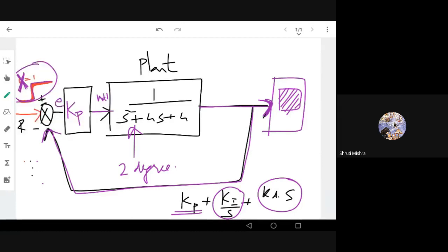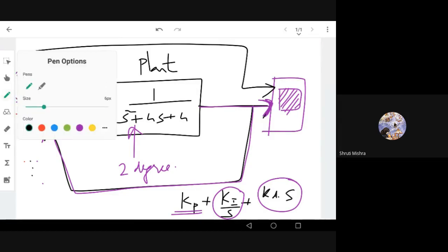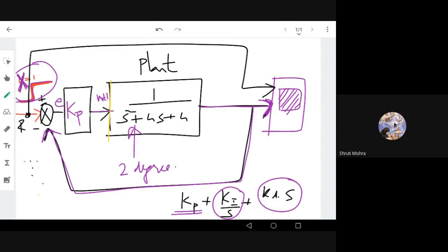So you also try to keep the reference signal in the scope. The two signals are given to the scope in MATLAB so that you can compare the change of output, etc. Right? So what we have done, we just made a transfer function model in MATLAB Simulink, or for analytic purposes, we just make a model. So the equation is 1 divided by s square plus 4s plus 4, the transfer function, right?